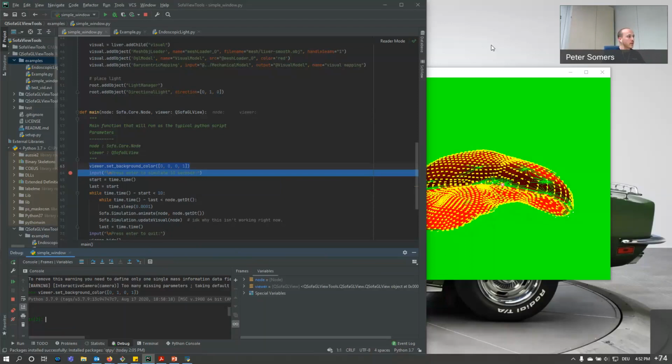MATLAB would calculate essentially what the tetrahedron coefficients needed to be for the uptake, and then pass that back to SOFA Python, and then we would update the internal uptake, or essentially diffusion coefficients, you could think of it as, and then rerun the simulation from the last one as a warm start. Cool. And then just run until convergence, basically.